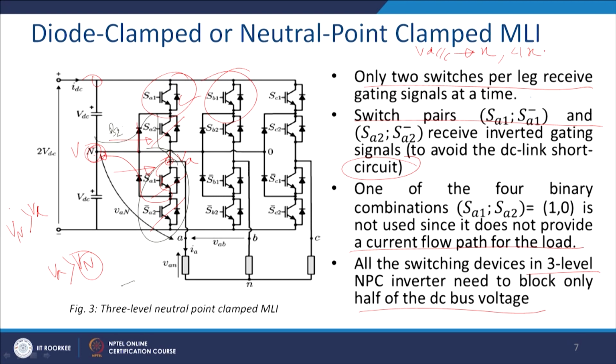But if the IGBT price at VDC is 2x, then you require 2 IGBTs, and it is again 4x. So, cost wise we do not have much problem, and in terms of benefit you get lower THD, a lower value of filters, greater longevity of your devices, and so on, all those advantages.